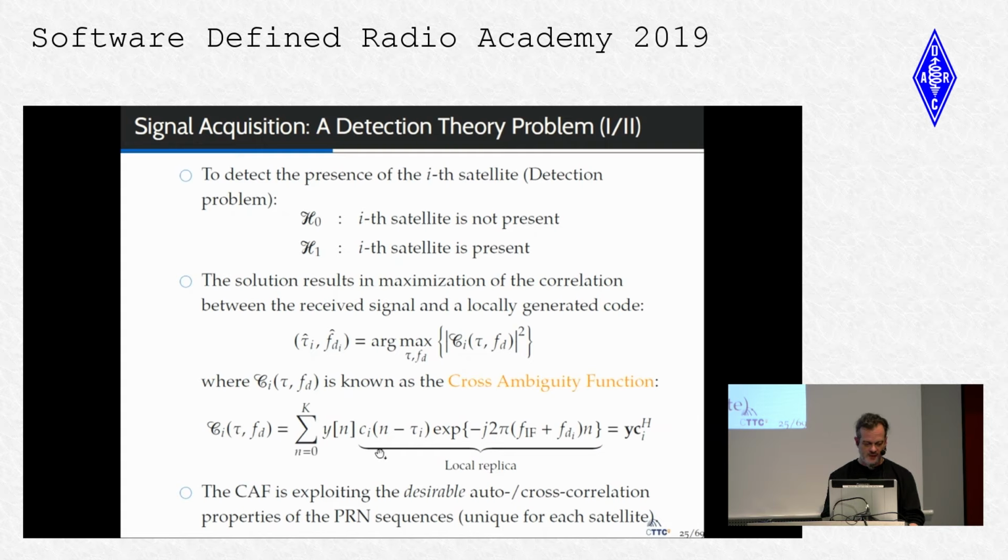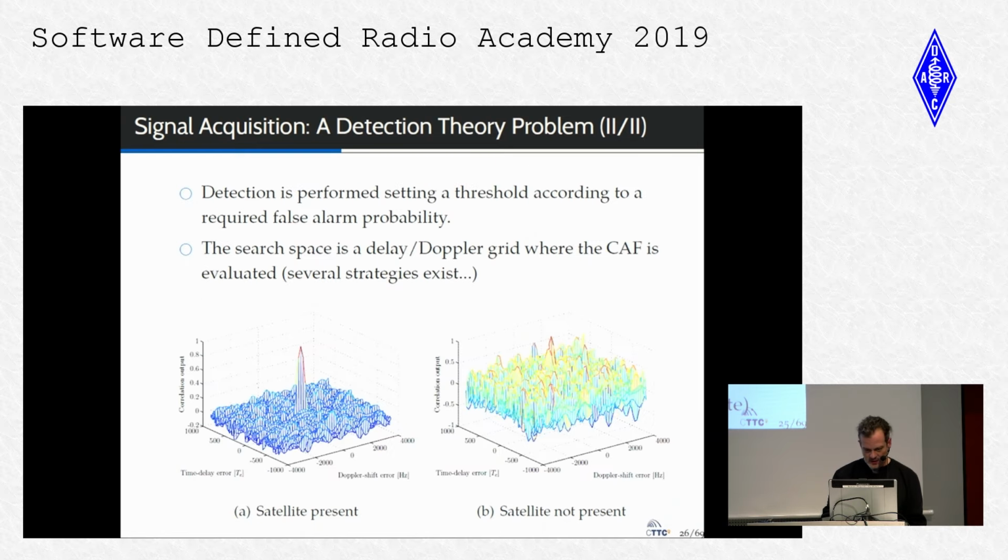multiplied by the pseudo-random code that identifies each of the satellites with different time delays. And you also need to multiply by different Doppler shifts in order to get the one that is conveyed here. So you will have a two-dimensional space search, one in time delay and another one in frequency, and you need to detect the peak of that. You can see it graphically here.